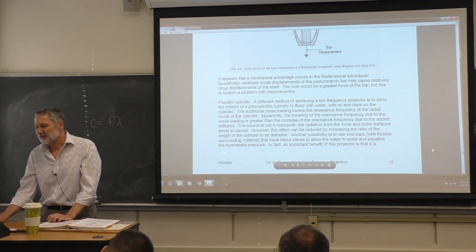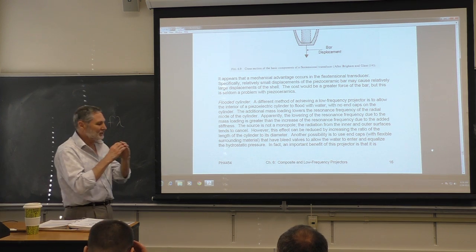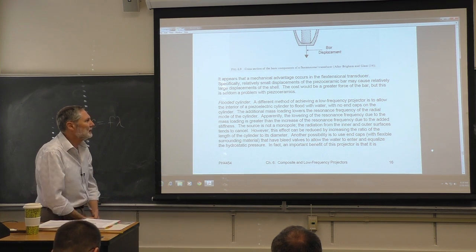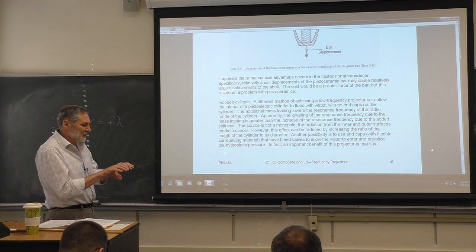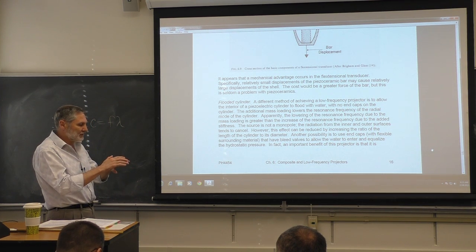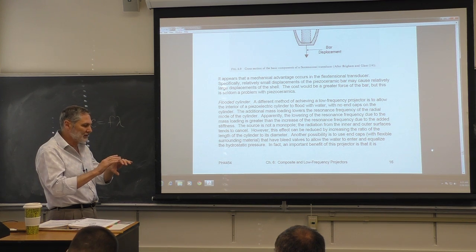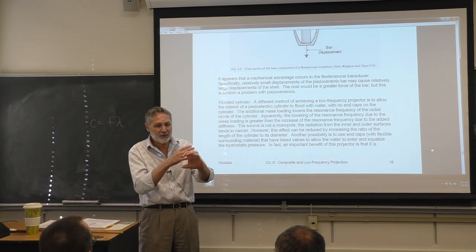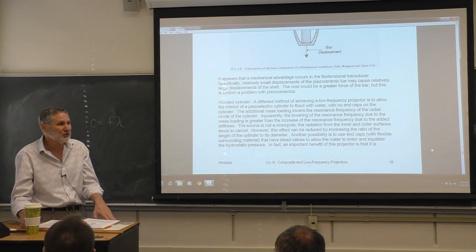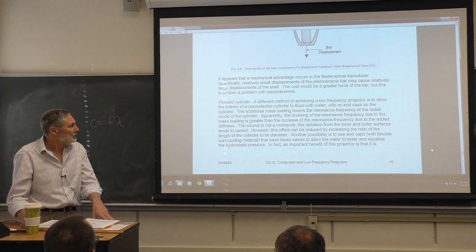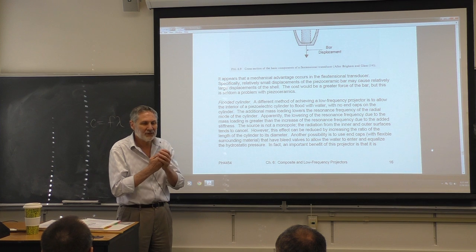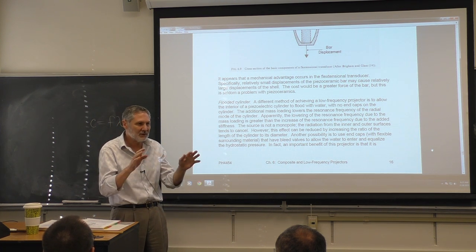Here's another thing that people have done, okay? Imagine you have a piezoelectric cylinder you're going to use as a projector. And the way we've been talking about it, it needs to be shielded from the water somehow. We'll talk more about this later in the course. But basically, we think of the water being the outside, and we think of air as being the inside. You can flood it, and they do this. You can have water on the inside. Now, of course, there are details. You need to protect the material, especially in a saltwater environment, but let's not worry about that, okay?